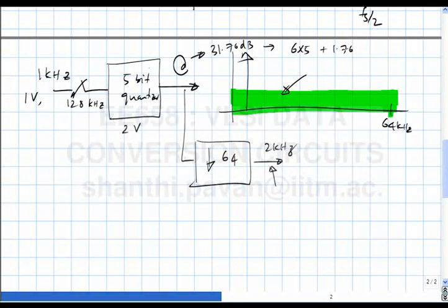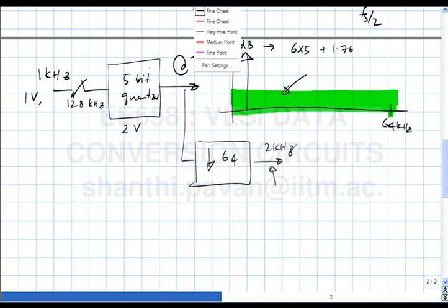Those who claim to have understood the previous discussion, can you tell me what will happen if I downsample the whole thing by 64? The noise will? Why do you think the noise will keep on adding up? So as you point out, if you look at it in the frequency domain, the noise spectral density will go on aliasing, right?